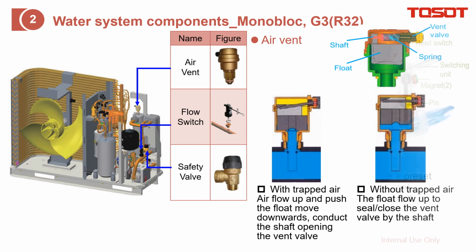Air vent mechanism. Here is how it works. If there is some trapped air here, then when the air goes to this area, it will go up to this one, and then release from here. It is automatic, no need to operate.